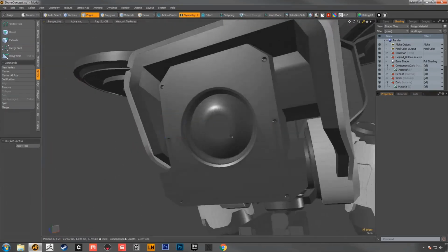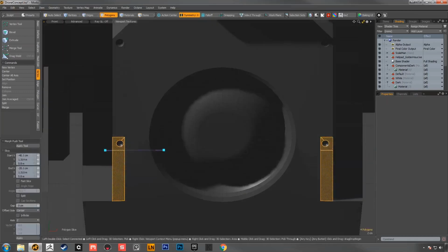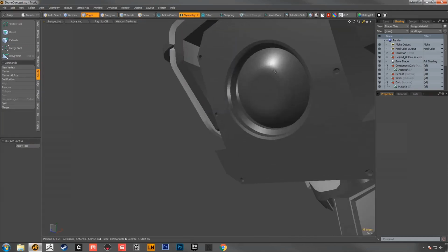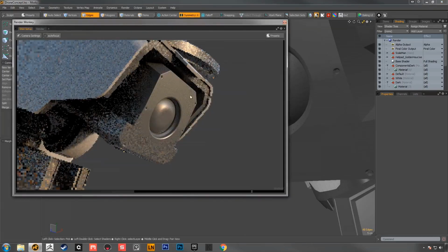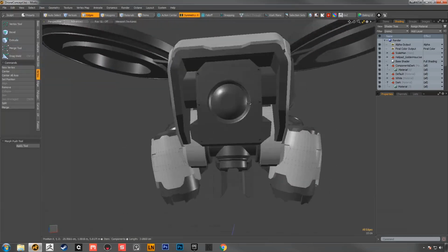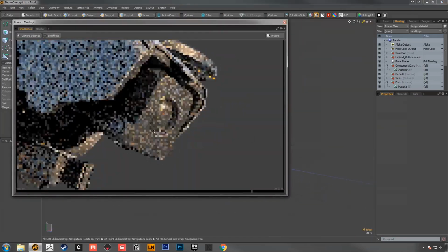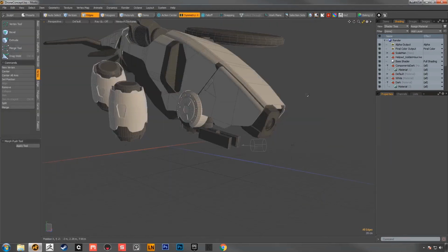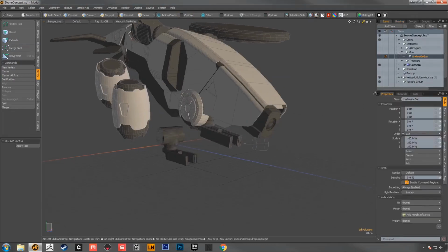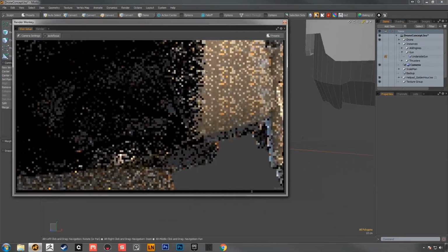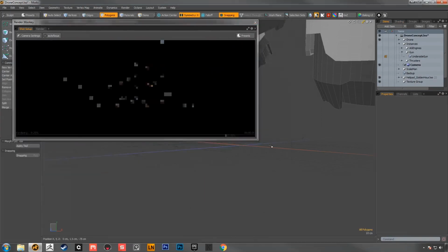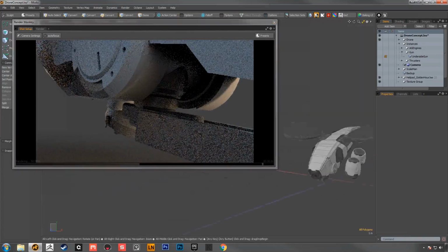I don't use Boolean union or adding shapes together very often, but to create these kinds of holes, it's a lot faster to create a new cylinder, push that into a face and Boolean it away, rather than trying to model that shape into the front of a pre-existing shape. Especially as you can imagine trying to do it into a curved face, it just becomes an absolute nightmare. So that's where I try and avoid doing that kind of stuff.